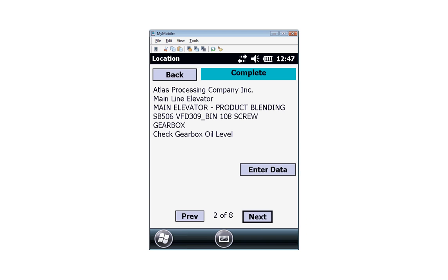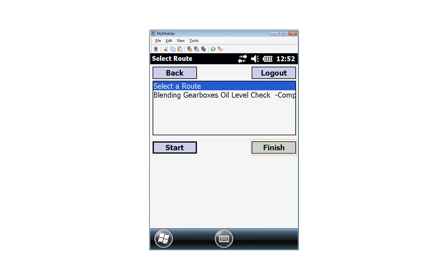When you have completed your assignment and you have entered data or a not collected reason for each location, you can finish the assignment. When you are at the last location in your assignment, click on the Back button. Note, if data you are entering is an alarm, you will be able to leave a comment which will be visible at the location in the assignment back in iReliability. You will now see a Finish button for a completed assignment where you saw the Check-in button for a partially completed assignment.